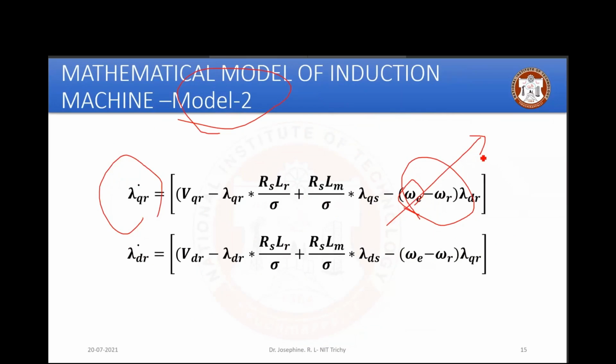If the rotor currents are also rotating at synchronous frame, meaning the stator current, then it may come into alignment with your stator air gap flux, and obviously the current will be 0. If the current is 0, then the air gap flux and your rotor positions are at the same alignment, there won't be any rate of change of flux, and then it becomes 0.